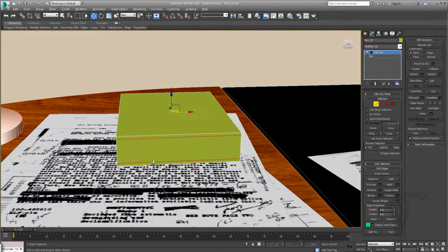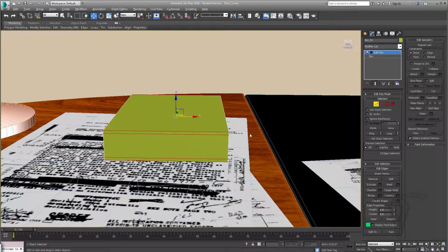Okay, so let me create the back side of the book real quick. So I'm going to select this edge right here, Alt-R. Again, it's just ring, connect, and I'm going to set the pinch down to 0 for right now. I'm going to slide it to my left and pinch them together. Let's go something like that and slide it. We got to pinch it a little bit more. And slide. Tends to separate a little bit when you slide it. So let's go right about there. Maybe a little bit more. Control Z. A little bit more in. Something like that. Check mark.